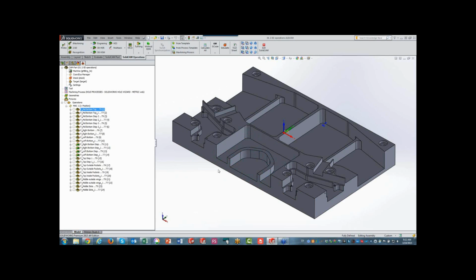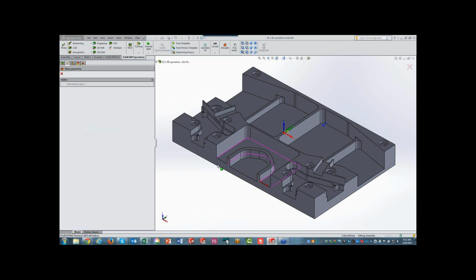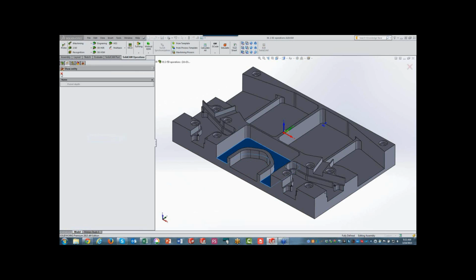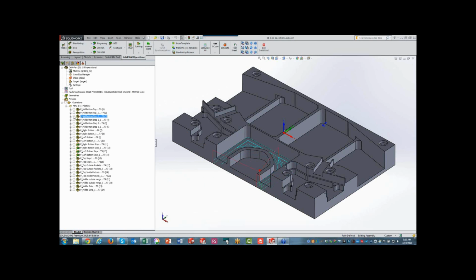But like I said, I had to then continue working on into this area. So my next operation was just a semi-finish, actually a finish for this particular operation. And you can see it working in this area on the same geometry. Now I want to go into my next operation, like I mentioned, and I want to mill out the next step. So I have to have a geometry just for that area as shown over here. Obviously, my Z levels have to be different as well. You can see my Z level bottom is over there. And if I show you the actual tool path of my operation, you can see that my tool path is including this area over here only.